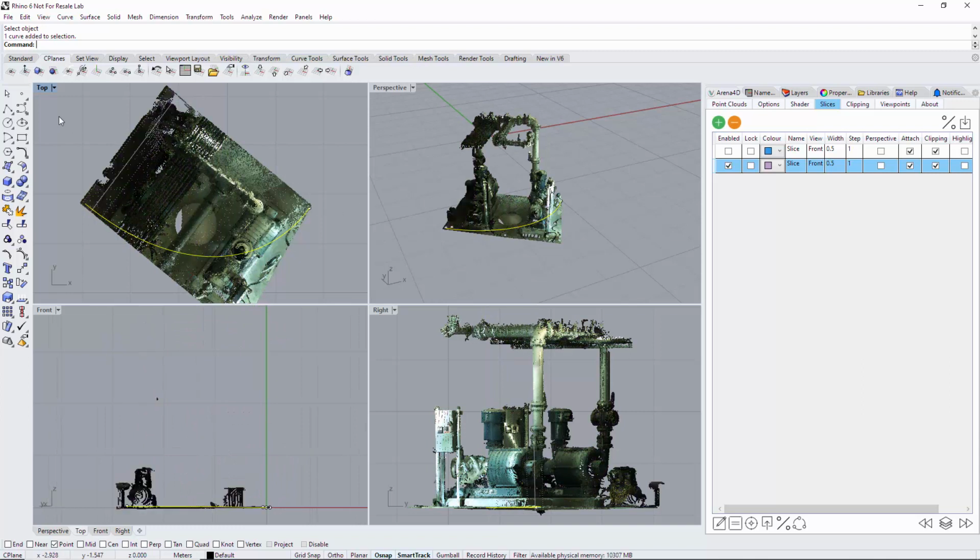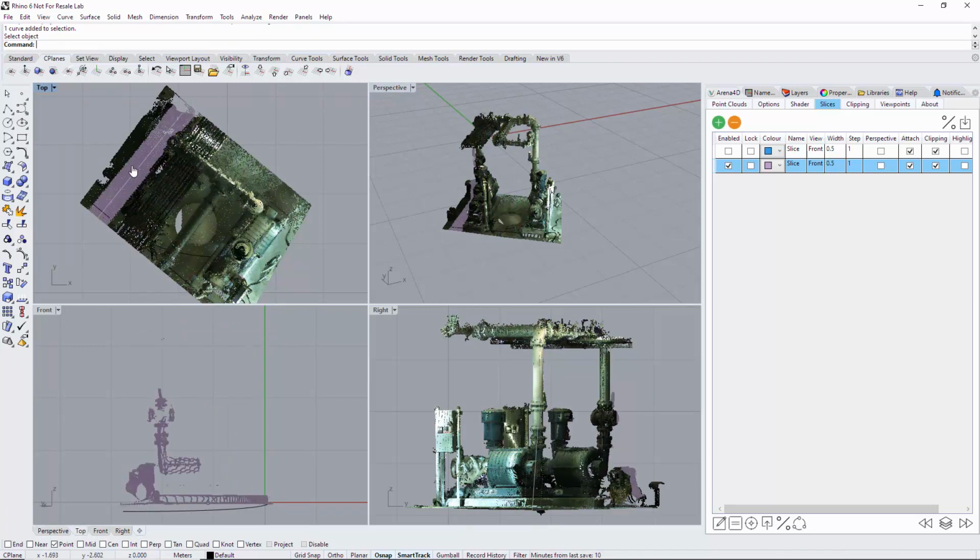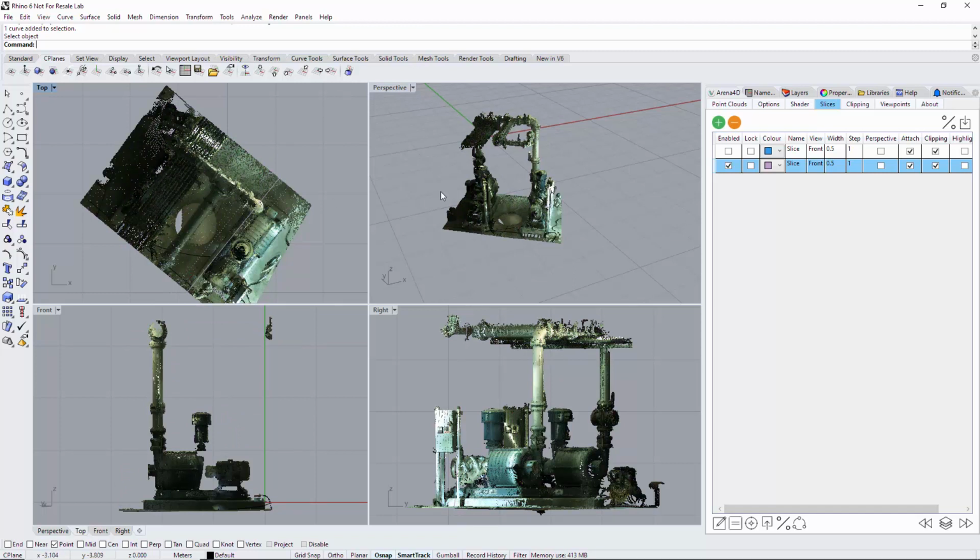Now you can actually draw straight lines. I did show you the 2-point slice, but I could actually draw a polyline on here. There it is, which is a straight edge. And I can click align to curve on that, so the correct slice is chosen. I'm going to click align to curve, make sure the line is turned off, click, select the line. Now that slice goes up and down against that line. So again, if you have straight edges and you haven't changed your construction plane or aligned the data, you could use align to curve and draw straight lines.